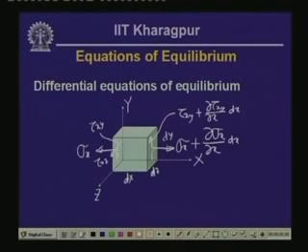We will have, in the z direction, tau x z, which is on this particular plane. So, when it is coming to this plane, there is a change over the length dx. So, tau x z plus del tau x z del x over length dx.